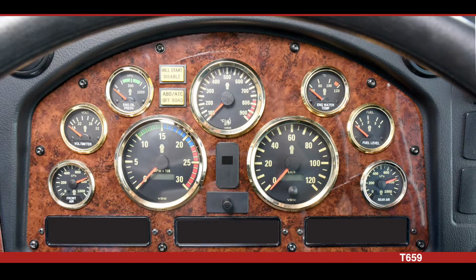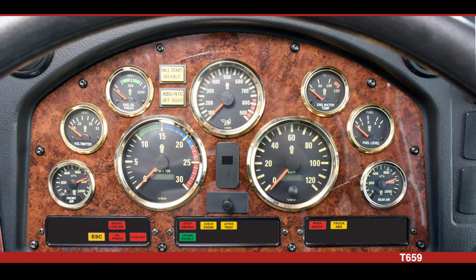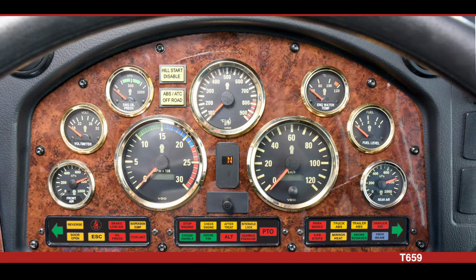The power on test. When the ignition switch is turned on, some of the warning lamps will illuminate initially, extinguishing in sequence. This test allows the driver to know the lamps in the module are in working condition. After the test, the module enters the normal operating mode, in which all input signals are monitored. If only one system is activated, the respective lamp will turn on, giving the driver a warning or status indication.